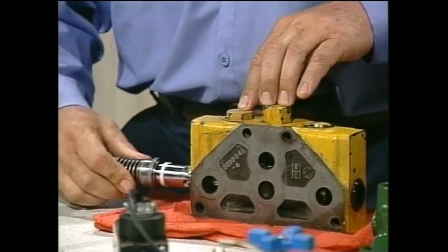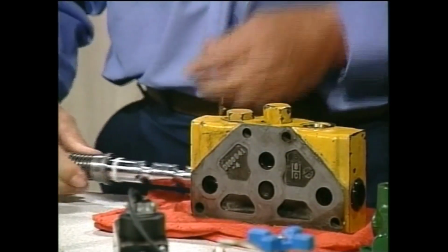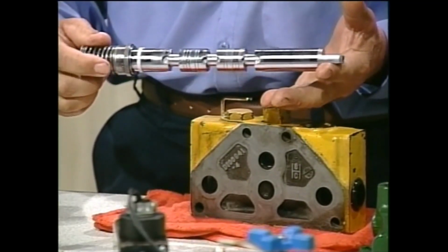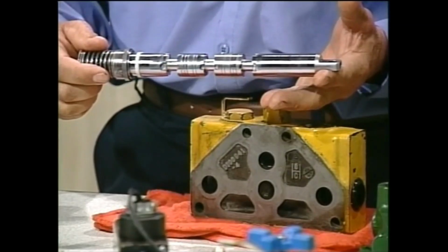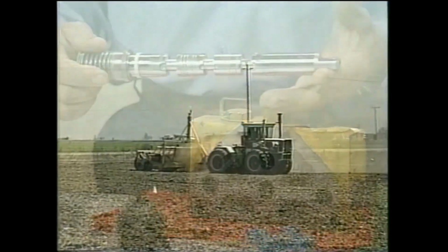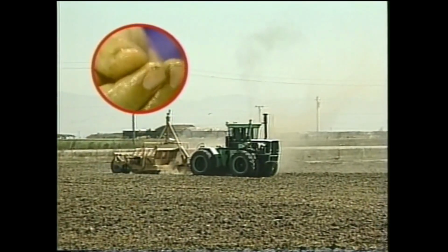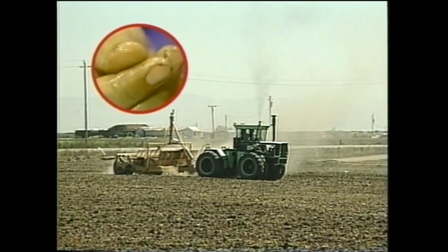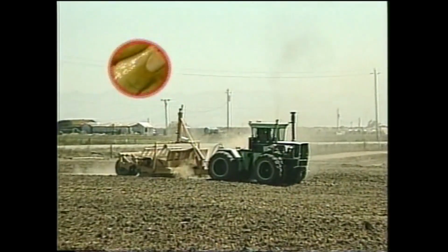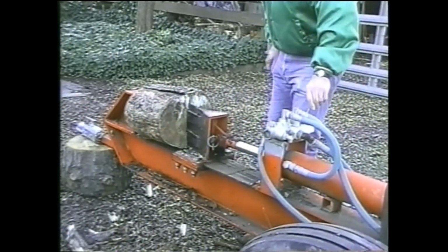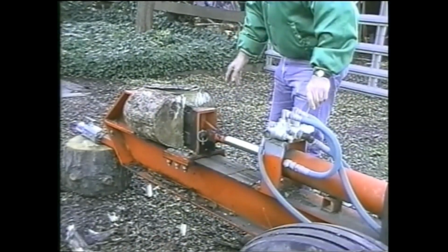Control valves are manufactured to a close precision tolerance. Most spools and valve bodies are so closely fitted they do not require any seals between the parts to prevent leakage. Just the smallest amount of dirt in the hydraulic system will act as an abrasive lapping compound that will lead to internal spool leakage. Spool leakage, as well as reduced pump flow, slows down the cycle time of hydraulic machinery.